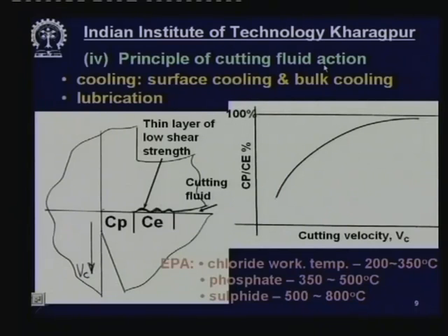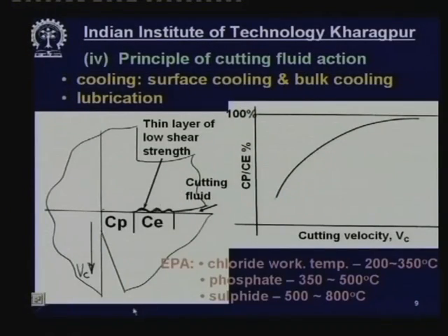Now, what is the principle of cutting fluid action, how really does it work? So, it has got 4 purposes: from bottom, protection of the surface, cleaning the surface, that is washing away, then lubricating and cooling. Now, how does it cool? The cooling it does,